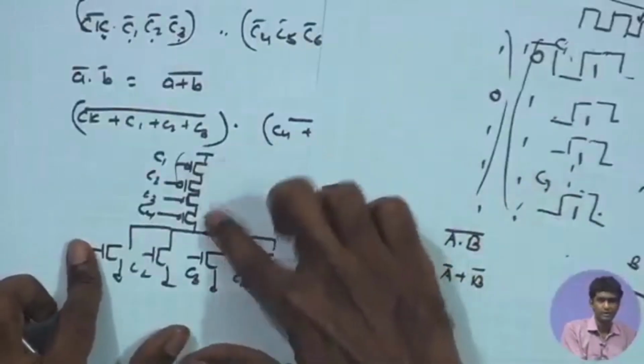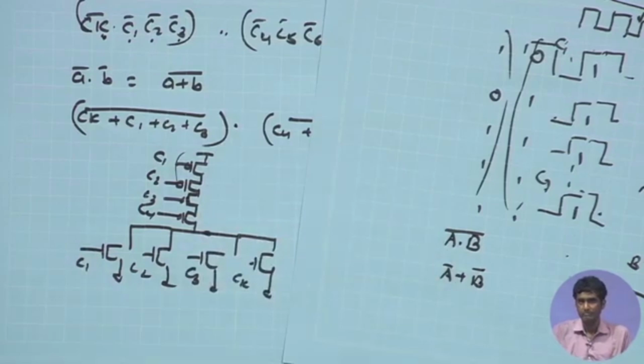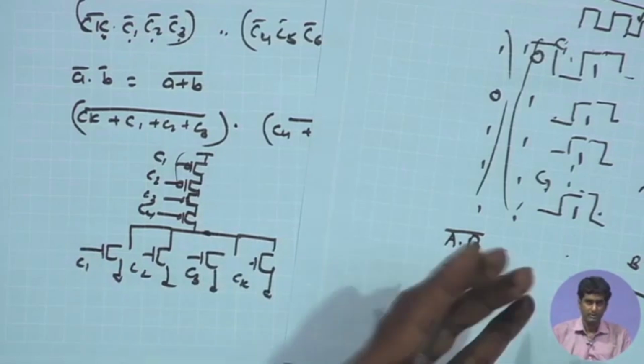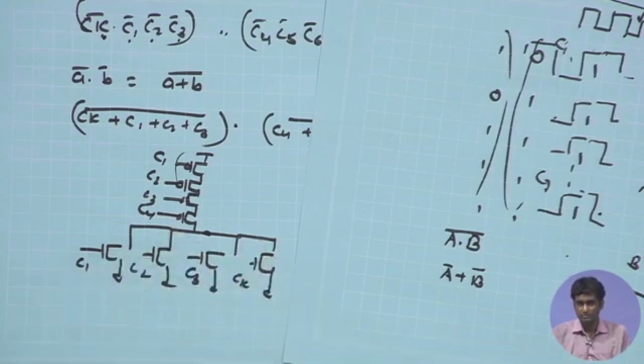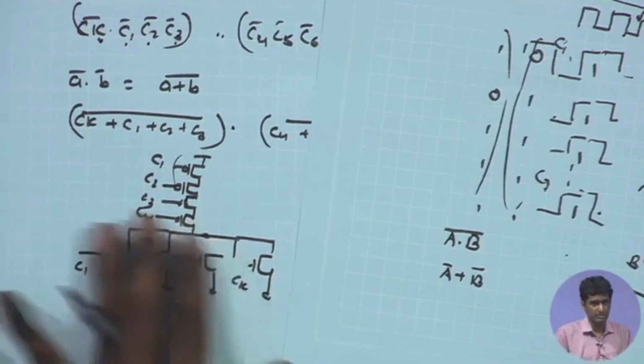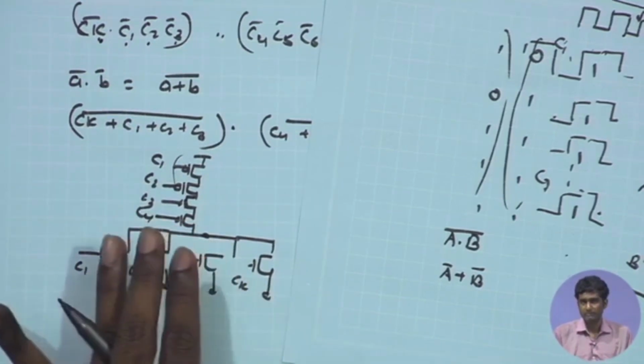The speed of 4 stacked NMOS transistors can be significantly better than 4 stacked PMOS transistors, because the mobility of the PMOS is 2 times lower in 180 nanometer. That difference has vanished for lower technologies. For lower technology nodes, that difference is very minimal, but for older technologies like 180 nanometer you will still get at least a 2 to 2.5 ratio.